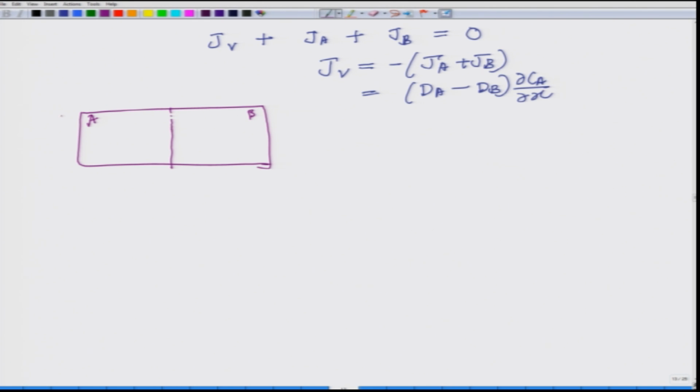And let us say that on the y axis we will consider x A. So, obviously, on this side we have 1 x A, and on this side we will count the inverse of this. So, x B would be like this. So, x B is equal to 1 at this point, x A is equal to 1 at this point, but at the interface there will be diffusion taking place, and therefore, the final concentration would appear something like this.